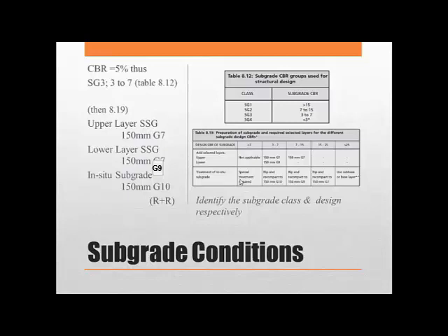For this design context, we elect the same subgrade group for all design areas of the road. See Table 8.19 for subgrade layers. The higher the value of the CBR, little or no subgrade would be required. Thus, after we select our catalog design, we are going to add our selected layers, and we will, when necessary, rip and recompact the in situ subgrade, or if necessary, we will stabilize it to reflect an acceptable CBR.